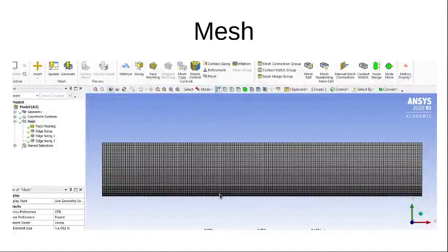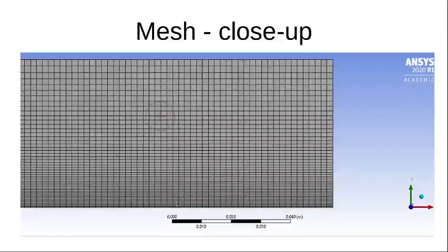That is like a much smaller in size, and therefore many more control volumes clustered around there. So if I show you the next slide, which shows the close-up view of this corner of the grid, it shows something like this. So you can see that near the wall, the grid points are much closer, because that is where much of the gradients are going to be there, and far away from the plate, the gradients are going to vanish, and therefore the grid can be larger.